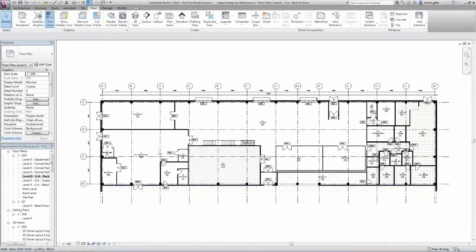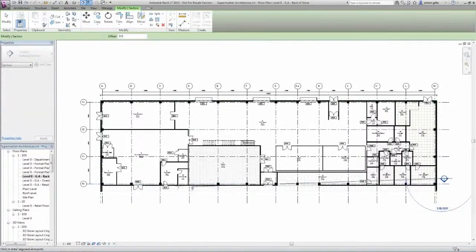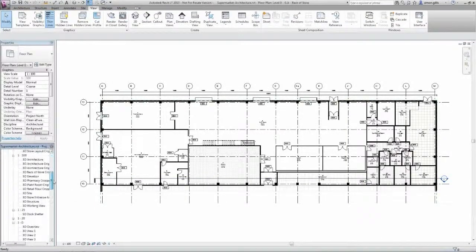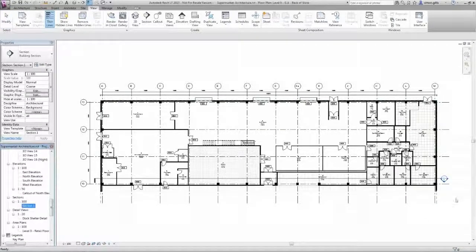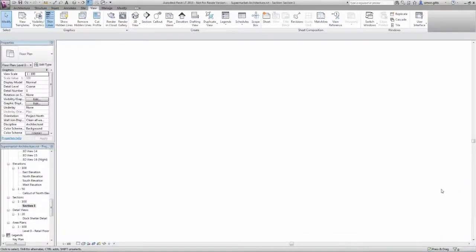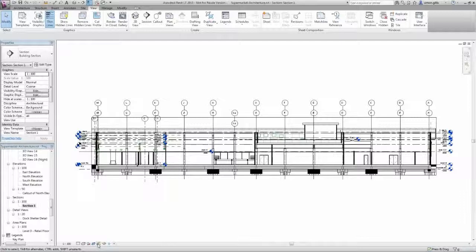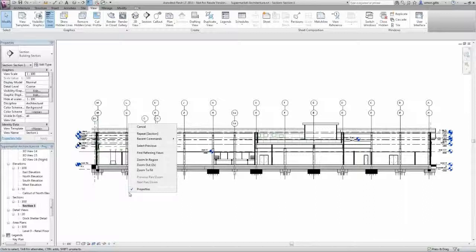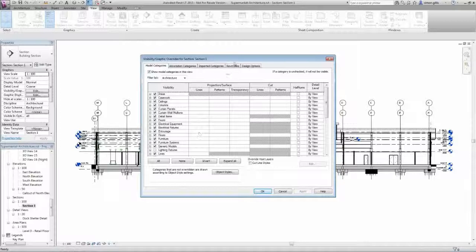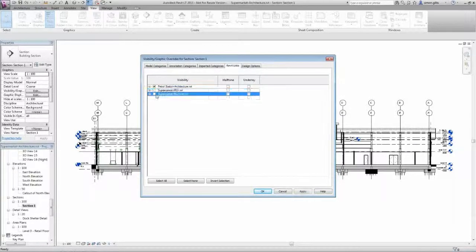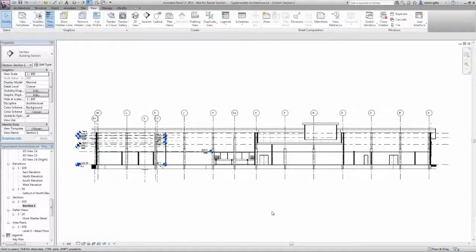Okay, so let's just move on and let's look at some other aspects. So I want to cut a section. Now when I worked in architecture many, many years ago, I was never a fan of creating sections. What I'm going to do now is I'm just drawing a section line through the model itself, as you can see. I can open that section from the project browser, and as you can see, I can also open it from the section tag. And I've now got my section opened. You'll see lots of information there. I've got some grids and things, levels, which have come from the linked models, so I can actually hide those just to tidy up my section.